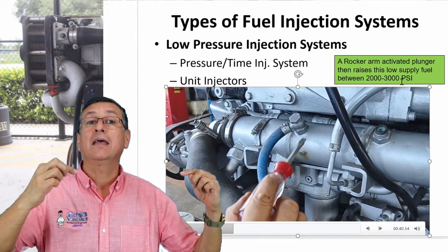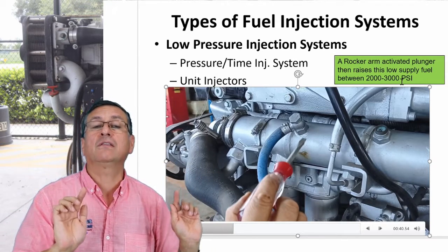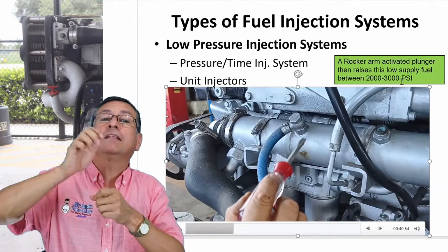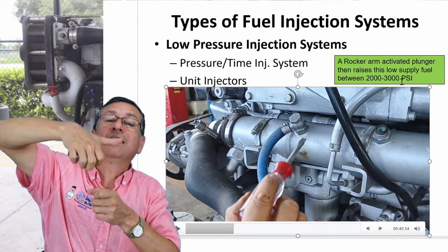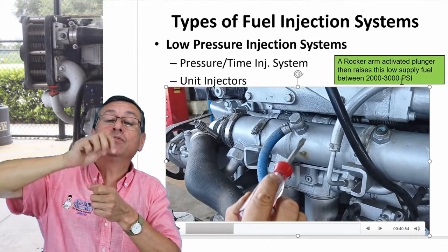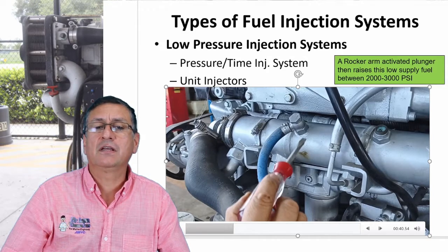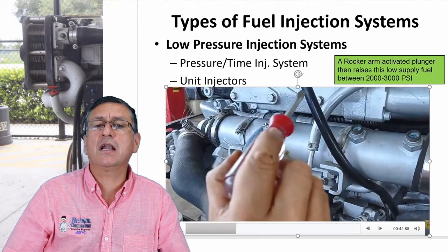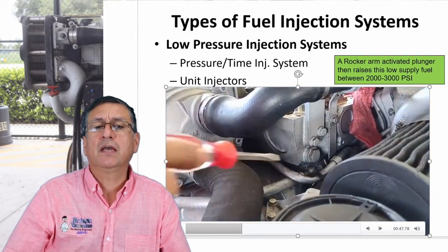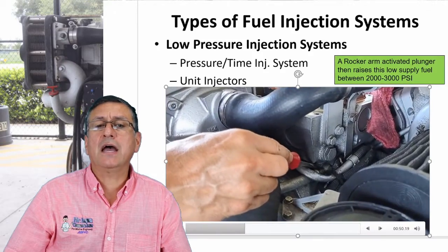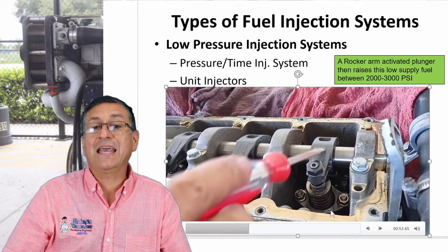And from the common rail, the fuel enters each injector, because the cavities internally in the head allow the fluid to enter the injector, and the injector only allows the passage of the fluid when the loads of the camshaft compress the injector. Right now we are going to check that procedure. Okay, my friends, the fuel continues over there and enters the head, in the cavities for the input. And right now, this is the injector.